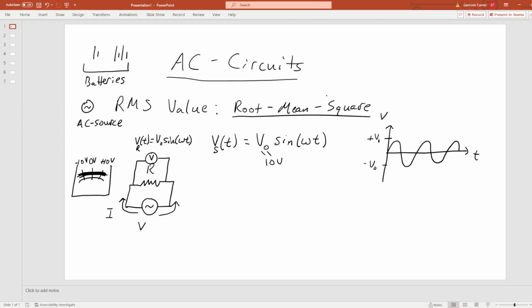The steps involved here are actually backward. First things first, we square the signal. So this is a sine signal, and the first step is to square it. The reason we do that is that puts everything on the positive axis.